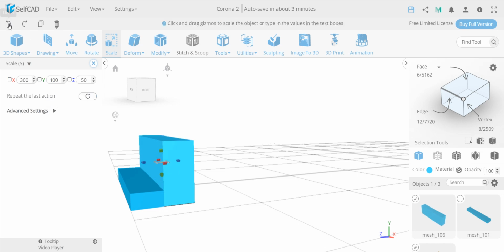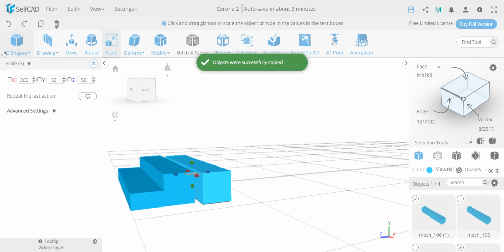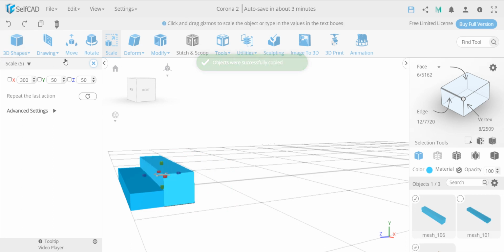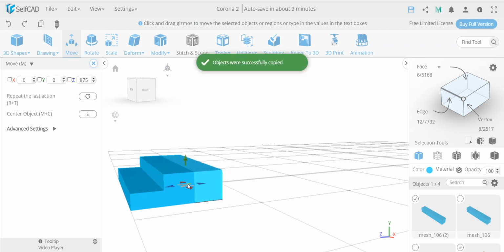So if I'm going to make multiple copies of this object, there are a lot of different ways to make a copy. For now, we're going to use just drag and drop, hold the control key into position to drop. You see this is not very easy in this case, so I can use the same idea, actually use the move tool. I can turn on my move tool and hold the control key and position like this. So it makes it easier.